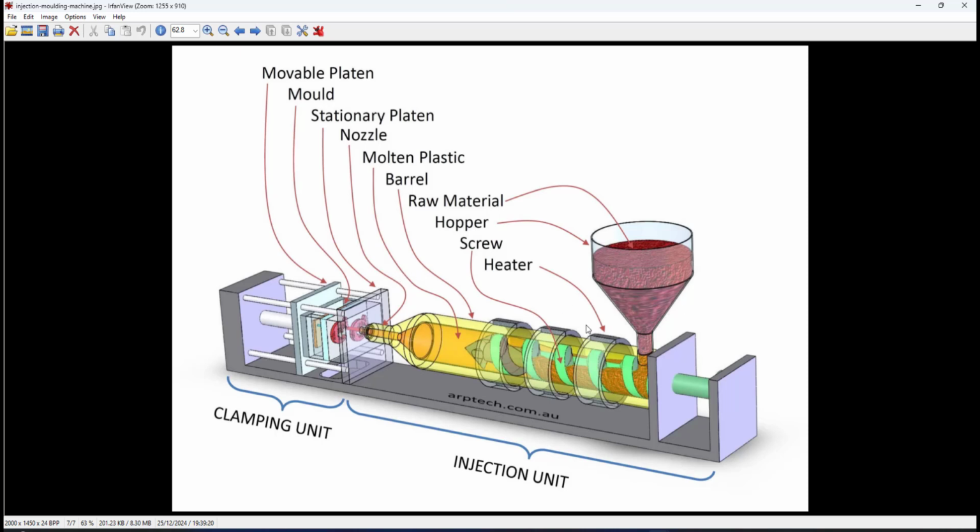In this injection molding, they have a feeder. They will put plastic beads here. So the plastic beads will be fed into the screw feeder. Due to high RPM, those plastic beads will be melted into liquid form, and this liquid plastic will be injected into the metal mold. So that's how they get your bottom casing. That's how they made the bottom casing.